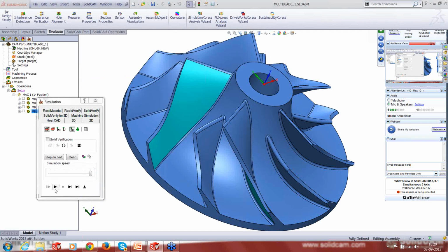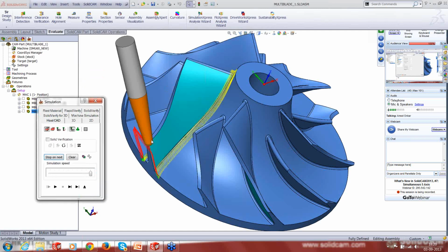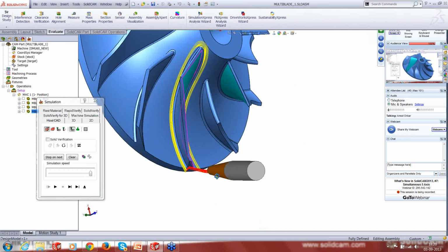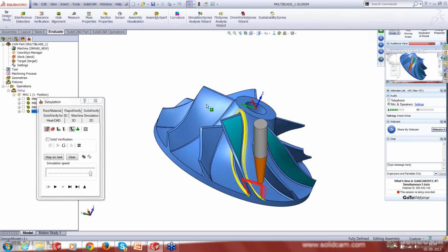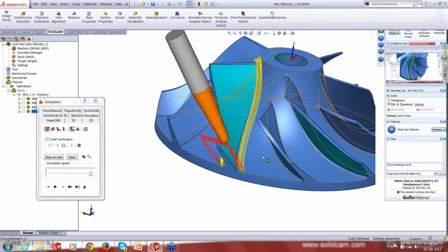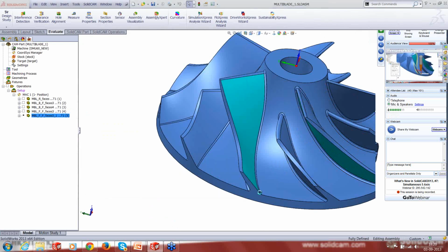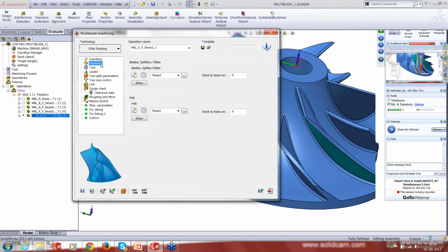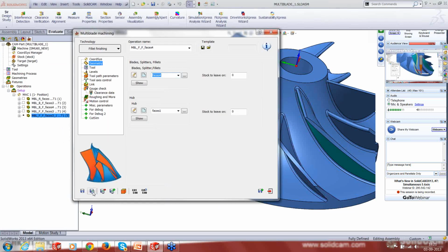Let's look at the toolpath. Very neat toolpath for the fillet. That would finish off the fillet. Right. I'm going to save and copy. And the geometry, again, I'm going to pick the splitter because I want to finish for the splitter now. And hit save and calculate, sorry.